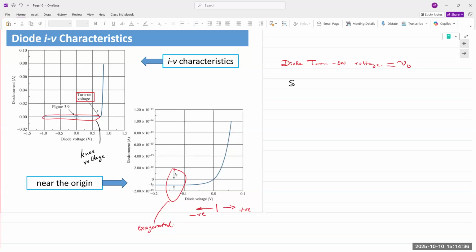These voltages are very well characterized. For silicon, it's between 0.6 to 0.7 volts. For germanium, it's 0.2 to 0.3 volts. Gallium arsenide is somewhere above 1.2 to 1.3 volts. Okay. And I'm assuming at this point, everybody is done with lab 3, right?